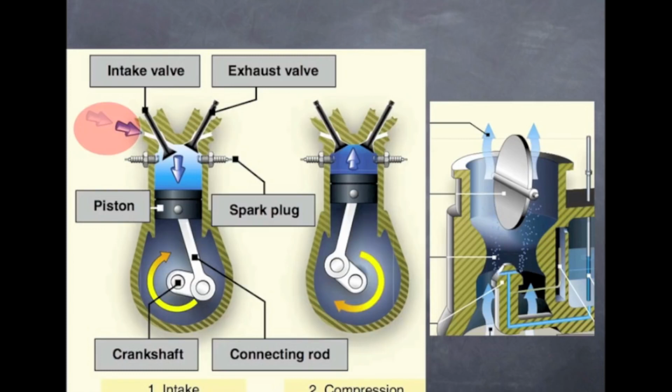And this is a tough concept. So if you could just look at that again over and over, and then know that when you decrease the RPM on this engine, there's going to be less air being pulled into the cylinder. Therefore, we will have less of a vacuum, less of a suction, and the pressure increases in the manifold.